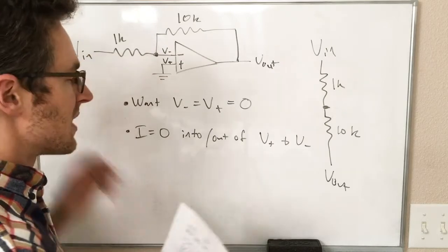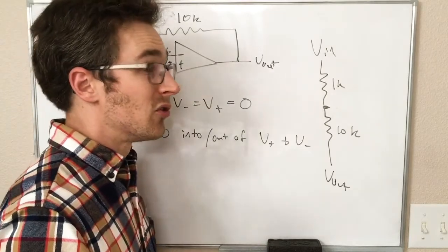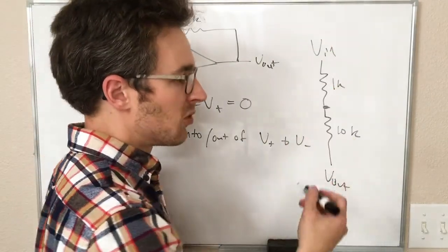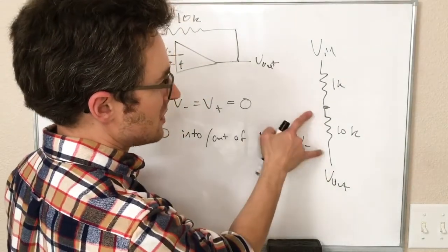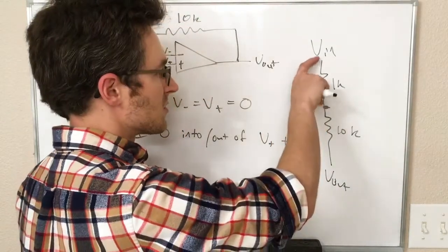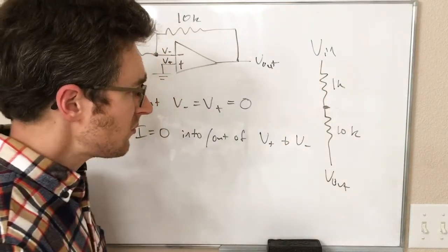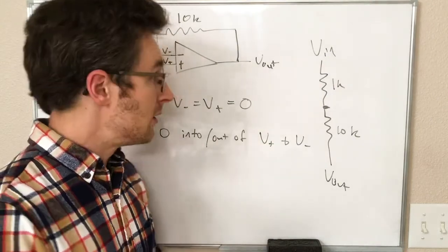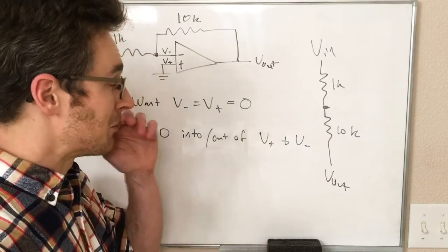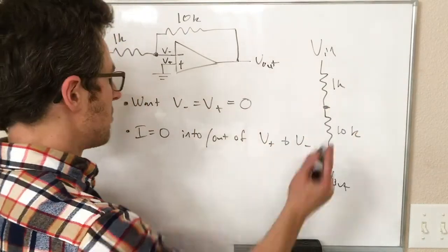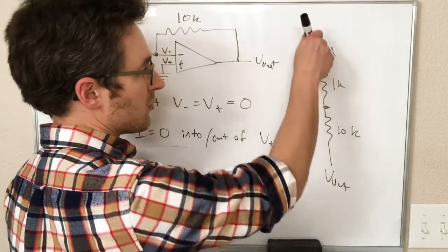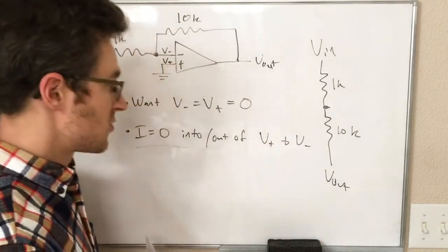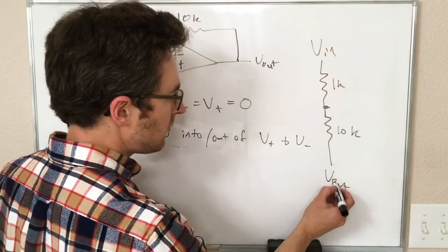The other piece, I guess, is that to derive the voltage divider equation, what we did is we found the current in this whole thing and then said, oh, okay, well, V equals IR. So the voltage drop you get for each of these things is that current times whatever this resistance is. Now, that doesn't work if they both don't have the same current. But we here have shown that they do have the same current, because there is no current exiting or leaving at this point because of the golden rule. And so the current through this has to equal the current through this, which means our voltage divider equation does work. Okay, so anyway,